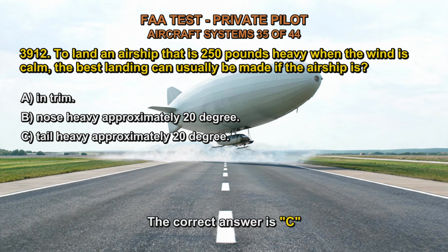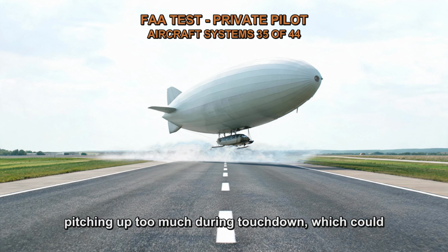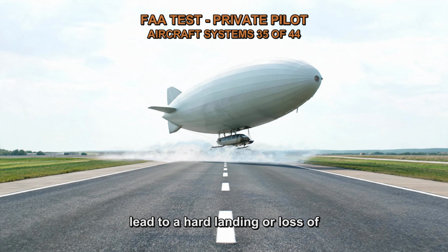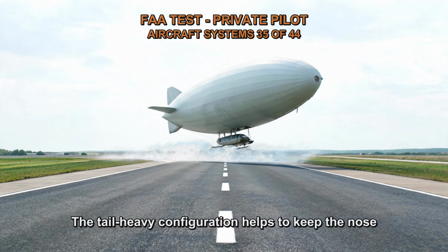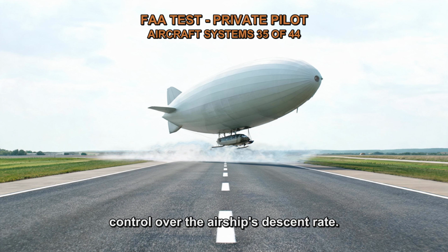The correct answer is C. By having the airship slightly tail-heavy, it helps to reduce the risk of the nose pitching up too much during touchdown, which could lead to a hard landing or loss of control. The tail-heavy configuration helps to keep the nose down, allowing for a smoother landing and better control over the airship's descent rate.